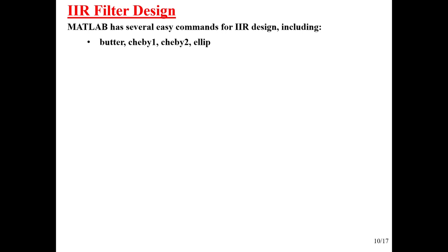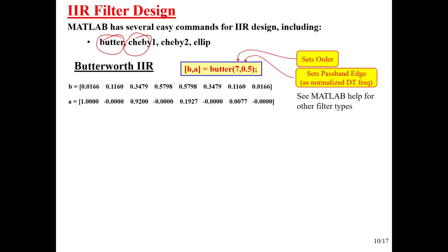But I'm going to focus on these 4 commands: butter, cheby1, cheby2, and ellip. Butter and cheby are named after people who pioneered either actual filter design in the case of Butterworth, or pioneered the math that went into filter design in the case of Chebyshev.